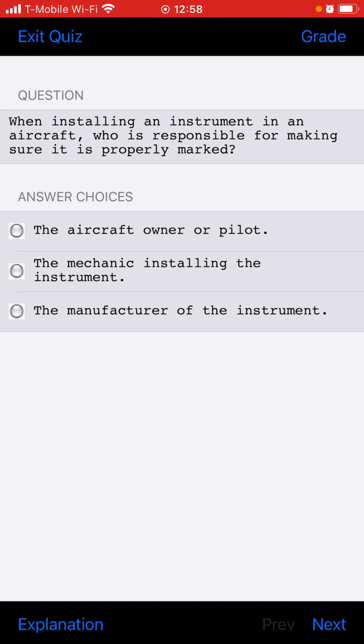What time should a gear retraction check be performed? During annual or other inspections and following hard landing.